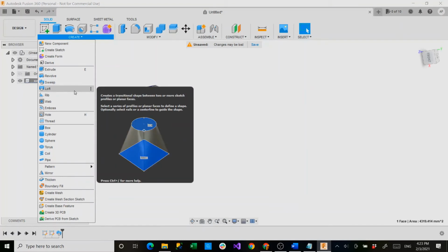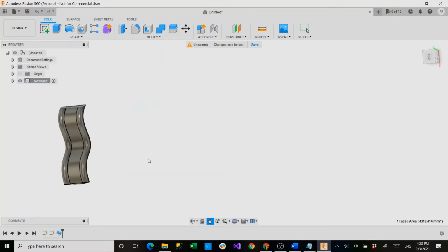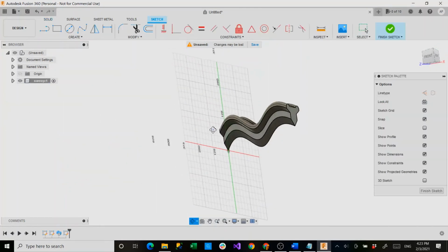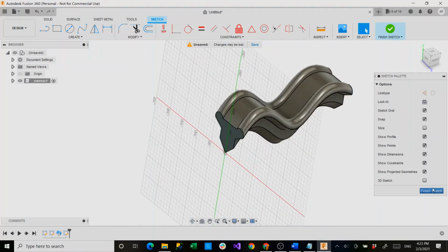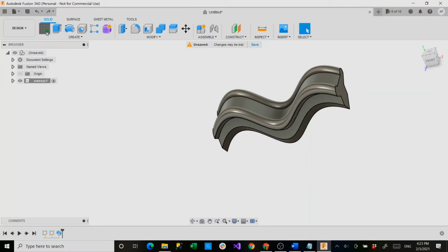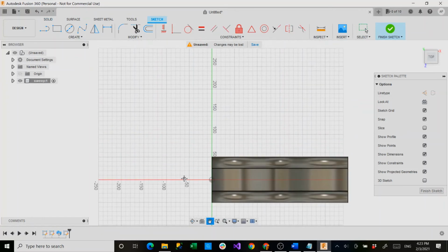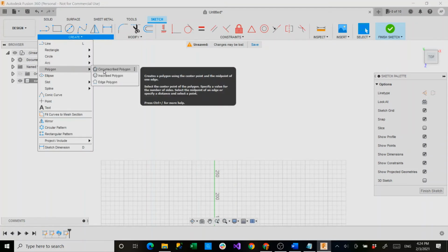So the loft profile uses two sketch planes and sets a profile between them that interfaces them. So we'll create a sketch, and we did accidentally select our initial face, so we'll say Ctrl-Z on our keyboard to end that. And now what we'll do is we'll create a sketch, and we'll go to our XZ plane. We use our middle mouse button to pan out a little bit, and we'll create a polygon that is circumscribed.